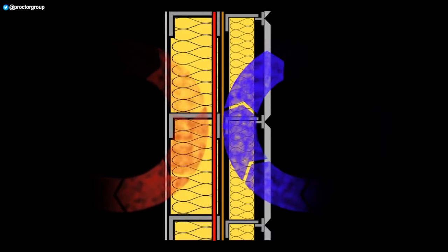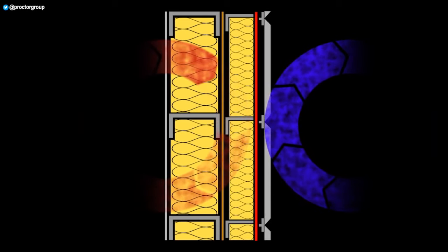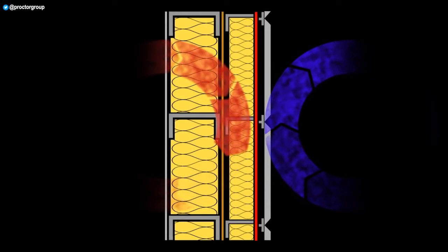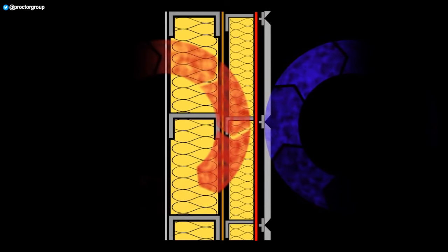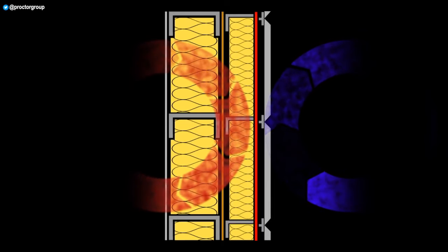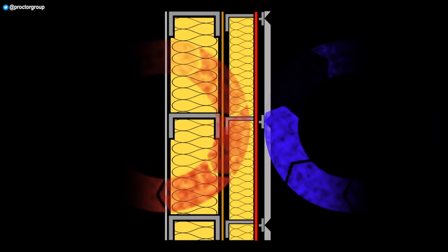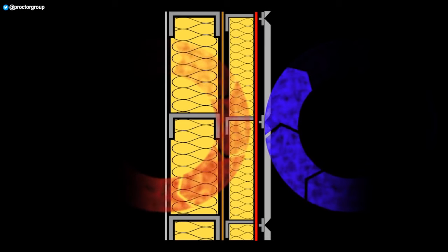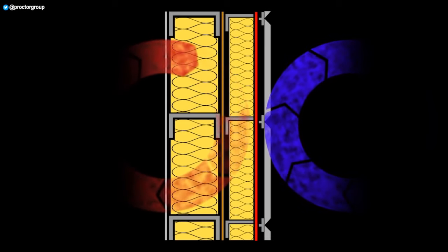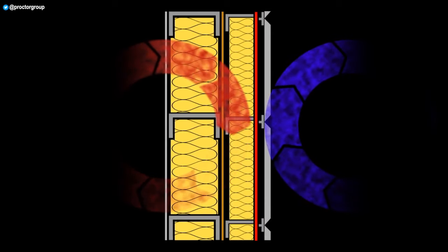By moving the air barrier to the cold side of the insulation, external systems such as our wrap-tight allow for an almost penetration-free airtight layer, which can be installed faster and more robustly. Far simpler than internal options, the wrap-tight external air barrier system maintains the envelope's integrity with fewer building services and structural penetrations to be sealed and less room for error. Being fully self-adhered to a substrate, it is also better able to resist external forces, such as wind loads, ensuring good performance is maintained by minimising wrinkles and poor sealing.